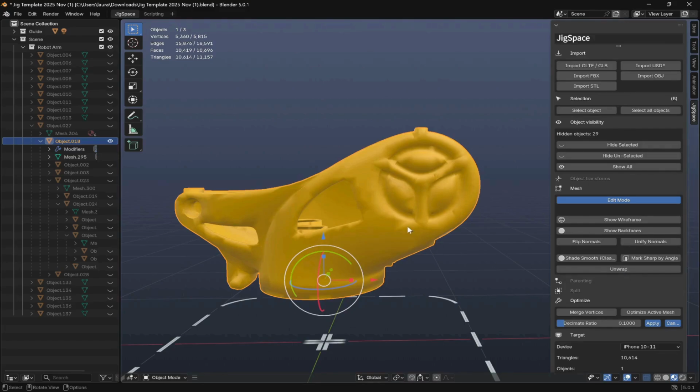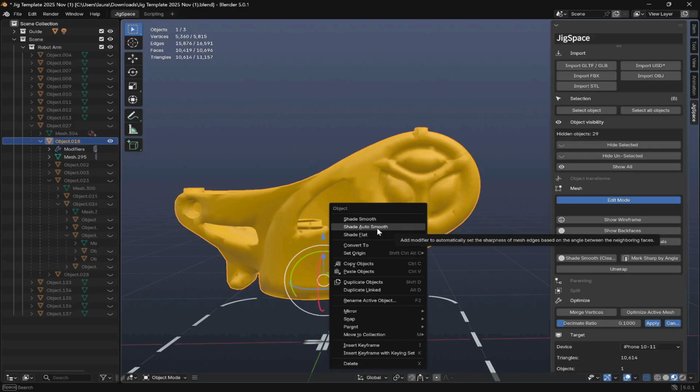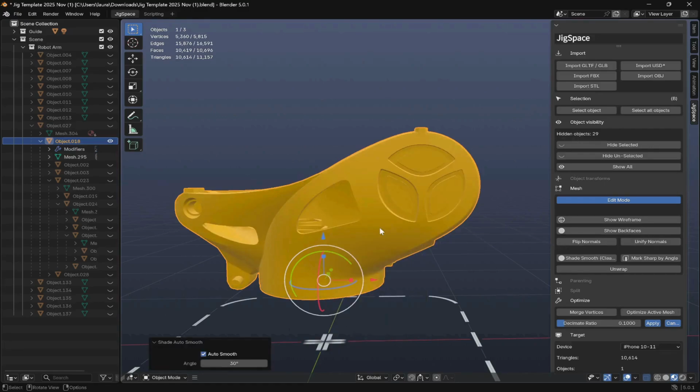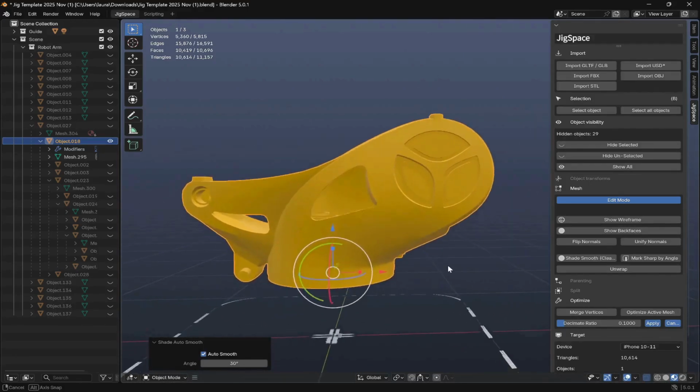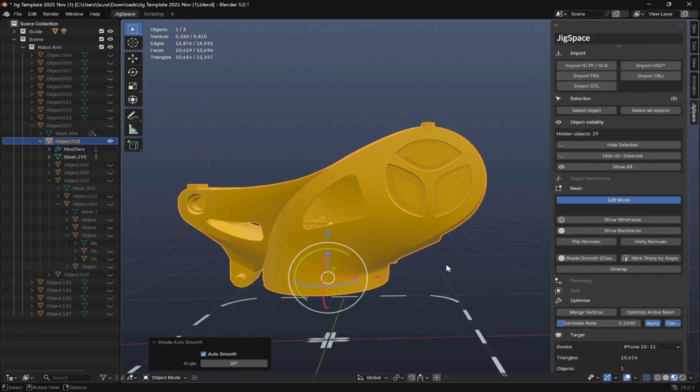And finally, if I right-click this model and set Auto Smooth on, you can see that we now have that nice smooth surface again. This is just making sure that all of our lighting information is no longer being drawn from the original CAD application that was baking this on. We're now using the real-time Blender template scene that we have our model in currently. So it's not relying on old information, it's going to be relying on new information as we make these Decimate changes.